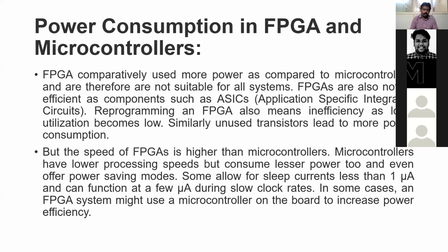For example, you can go for a latching application in industry, or a sensor in off time. The sensor needs to be on, but that doesn't mean the sensor should go off to save power. Even if you put it in idle or sleep mode, the sensor will be inactive and consume 1 microamp, so the battery power consumption will be very low. It is a very huge advantage over FPGAs. With microcontrollers, you can go for such applications.